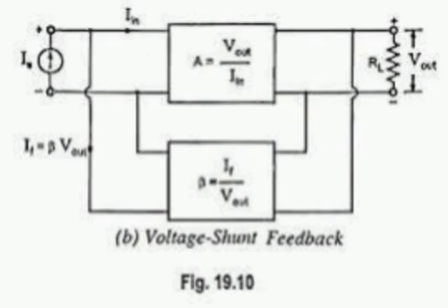If CC is considered, FL equals 1 in the numerator, denominator 2 pi CC (RD dash plus RL). If bypass capacitor CS is considered, FL equals GM, that is the numerator part, divided by 2 pi CS. If CB is considered, FL equals 1 in the numerator, denominator 2 pi CB into (RS plus RI dash).